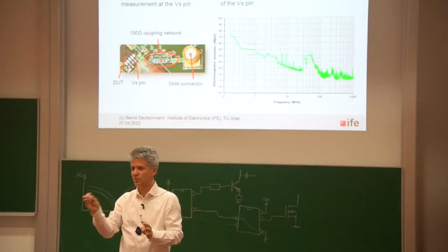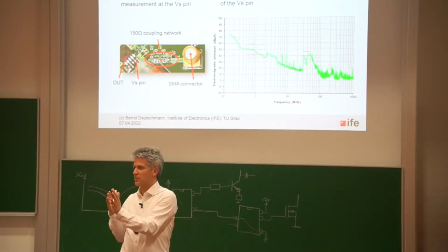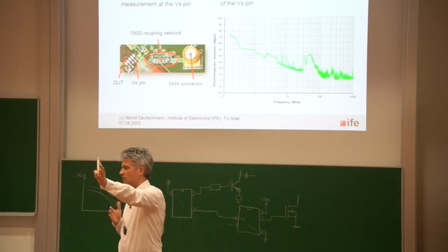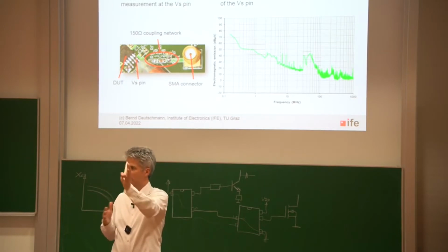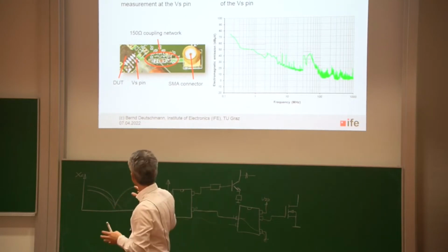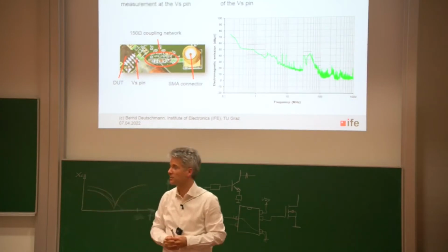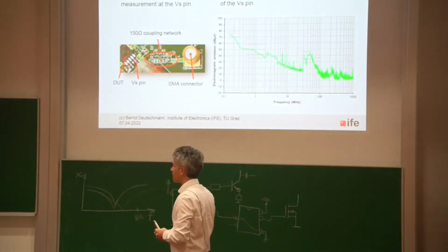This is possible. But let's suppose this is also the case, then all the electromagnetic emission that I'm measuring is at least sometimes in one phase, and I'm measuring the maximum electromagnetic emission of all these noise sources, especially when I'm using the peak detector. I have not mentioned the detectors yet, but let's suppose it's the peak detector.